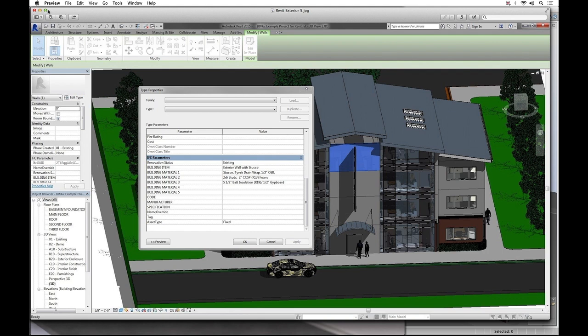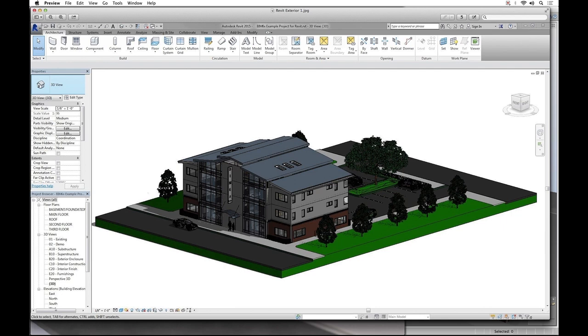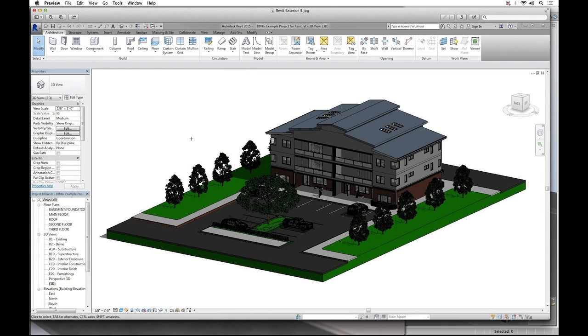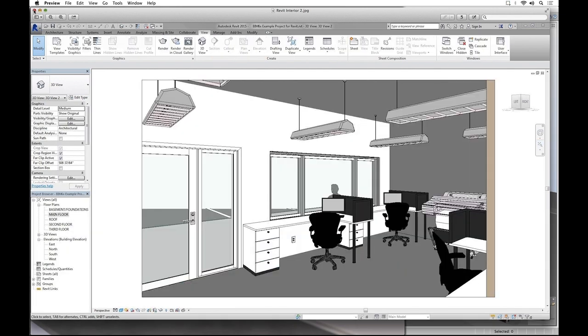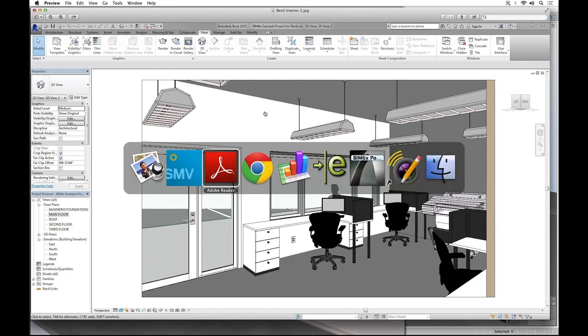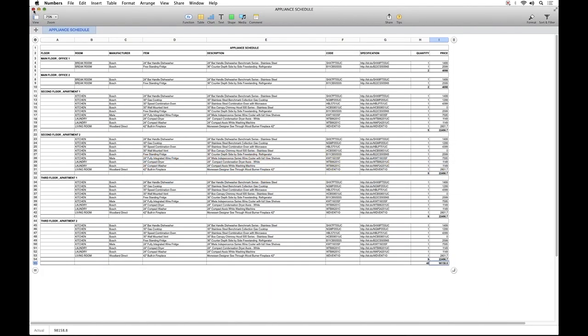Okay, now we want to show you this exact same project that we leveraged through IFC, brought into another software application that you can see here, Revit. What's nice about this is we're able to show that our geometry and our information comes straight over. So this was pulled into Revit, and the geometry and data are, you can see, here. It's the same project in ArchiCAD. This is it over in that other software application. Okay, so just showing that we can leverage that information in different applications if we want.